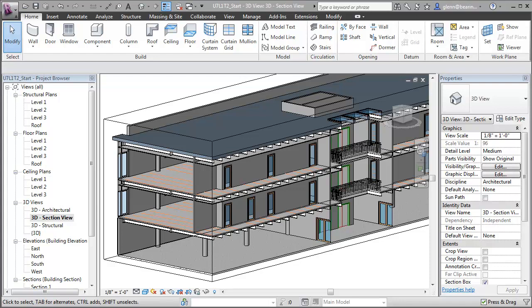Typically, the structural layer will go up first, followed by the finished layers being applied at a different time. It also creates inaccuracies for quantity takeoffs, because the quantity of the materials for the layers at the inside of the wall are typically less than the quantities at the outside surface of the wall. And while this may be a small difference for a single wall, across an entire building this can add up